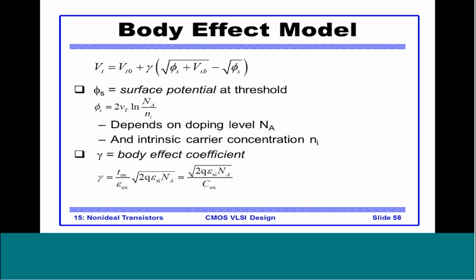So again we define a constant called VT0, which is nothing but the VT of the device considering VBS to be 0, plus we define a factor here which is the body effect coefficient, and here we see the definition of the body effect coefficient. I believe that you would be studying this effect in more detail in your device physics. So this is just a recap of that.